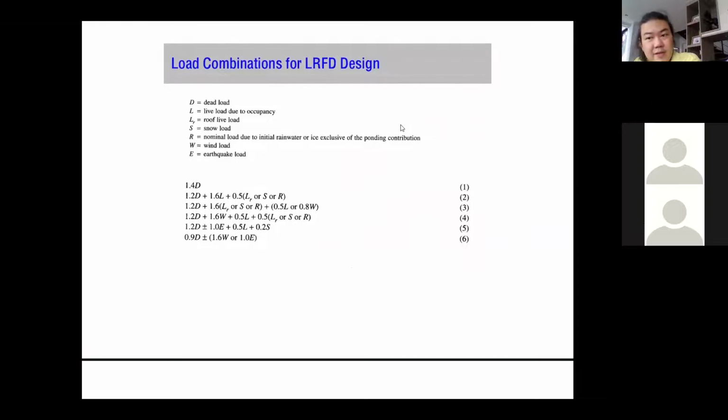And one more thing that I didn't mention in the beginning is the load combination. Generally, not all the loads can occur at the same time, right? Can you imagine that you are in the building where the maximum earthquake will occur while there's a full occupancy in the building, like everybody is in there, and then maximum earthquake occurs along with the maximum hurricane and stuff like that. If you want to design something like that, that means you're going to end up with a very, very humongous structure. So it's not practical. All right. So we need to consider the load combination, which one can occur for real, and design our structure so that it can withstand the proper load combination.